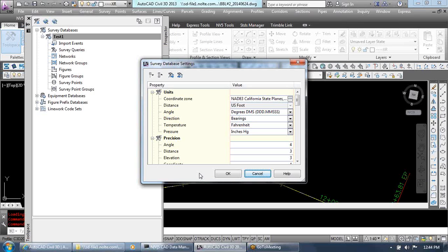So I'd like to see us develop the survey database and then, in the office, use the database instead of the CSV files. Couldn't they do the same thing? If you guys are using just a point drive, you could still open that point drive and set the database in that drive and have all your points and point groups. You set it up the same way, and then you can just extract that in. And they're all still in the database.